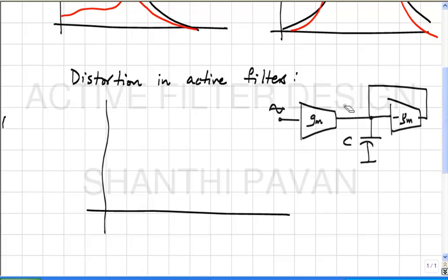Okay. Now, can you comment on this? So clearly, putting a high frequency tone near the band edge is out of the question. It is not, within quotes, an honest thing to do. So then I say, okay, I will put a tone at very low frequency, so that all the harmonics fall within the pass band of the filter, so that the filter is now, within quotes, not filtering off any of its own harmonics. Correct? Now let's figure out what happens at a very low frequency tone. So the frequency is very low.